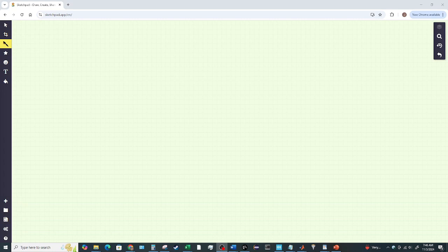So ultimately, what we want to do is control the stepper motor, right? We want to make it move a number of degrees. So we need to be able to translate numbers of pulses to degrees of motion in the stepper motor. But also, if we want to make it move at a certain rate, that's going to require a little bit more calculation, so we know how fast the pulses need to come to cause the stepper motor to move at a certain degrees per second rate, right? Okay, so all of these things are basically controlled by the characteristics of our PWM waveform, right?